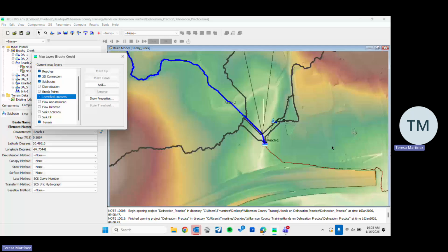And then also, after we run an initial run, sometimes we also need to check maybe there are some streets that would alter your drainage pattern, but the terrain didn't reflect that correctly, maybe a street that has a culvert underneath, like this case.